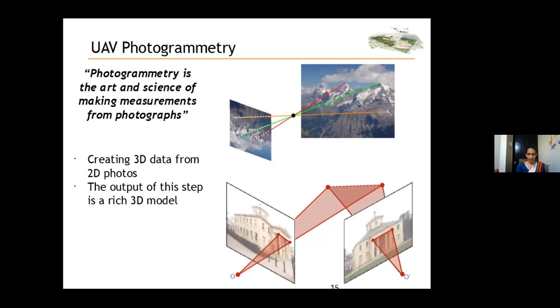You can see here as an example, we have two photographs taken from two different camera locations, but considering the same object area, so you can see the same information in both photographs. Now I can select one image point from the first photograph. This is my image point. If you go to the second photograph, I can see the same point. This one is the point related to this image point.